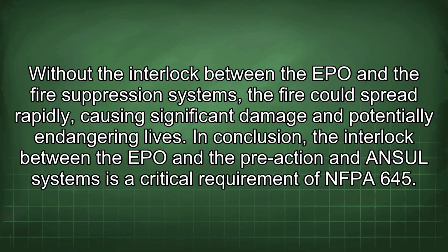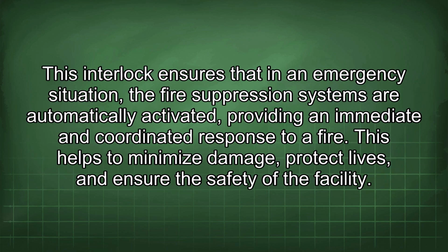Without the interlock between the EPO and the fire suppression systems, the fire could spread rapidly, causing significant damage and potentially endangering lives. In conclusion, the interlock between the EPO and the pre-action and ANSUL systems is a critical requirement of NFPA 645. This interlock ensures that in an emergency situation, the fire suppression systems are automatically activated, providing an immediate and coordinated response to a fire. This helps to minimize damage, protect lives, and ensure the safety of the facility.